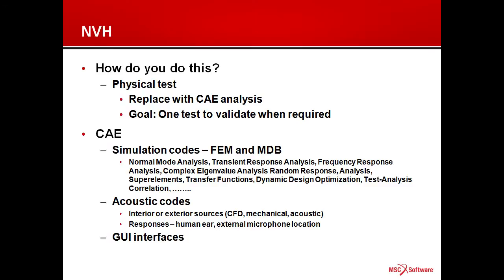We still do physical test. The idea, though, is to replace it with CAE analysis. The goal, of course, is one test to validate when it's required. There is some CAE work, at the very basic level, where analysis is perfectly fine. Then when we get into simulation codes, FEM, multi-body dynamics, for us it's Marc, Nastran, Adams. All of these solutions that I've listed out here, everybody knows what these are, normal modes and so on. They are always part of the CAE work.